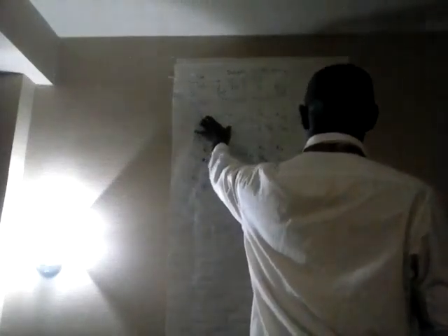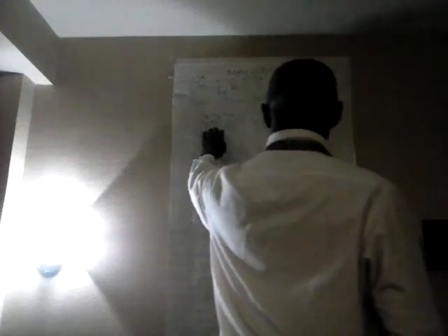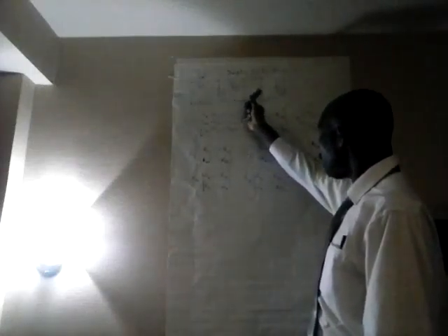this is all taking the determinant of this 3x3 matrix here, the source 3 by 3. And this is without regard to the mutual sign of the elements in the mutual resistances. They take on a negative sign. All the mutual resistances take on a negative sign. So we have minus R23.